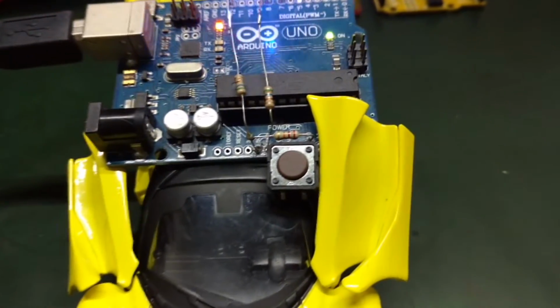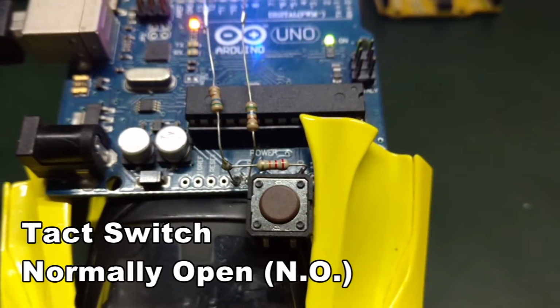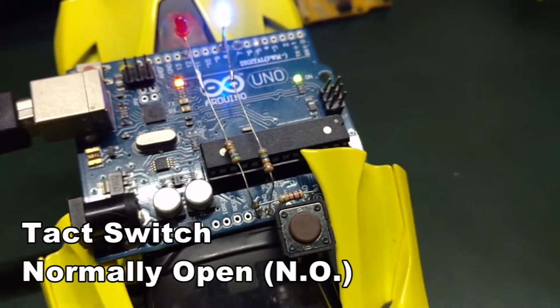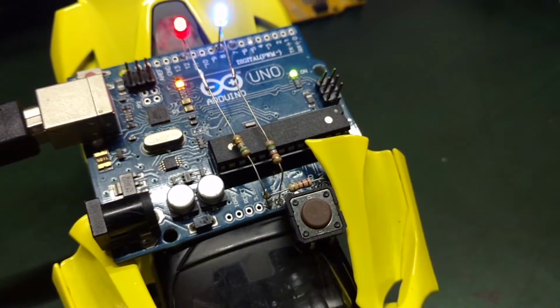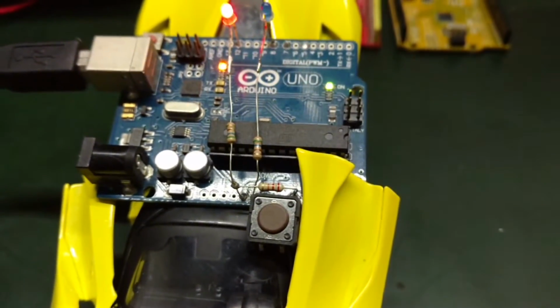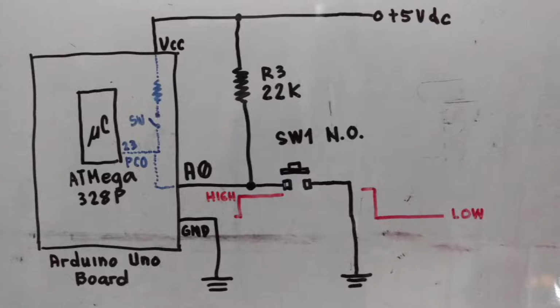By means of the switch. This switch here is a normally open tact switch, which by default is logic high. When I depress the switch, it goes to logic low. Here is the schematic diagram of interfacing this switch to the Arduino Uno board.